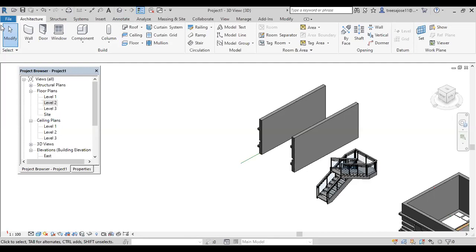Actually, with the help of roof by extrusion, you create the structure. Then after that, go to the void form. Then remove the internal structures. With the help of that roof by extrusion and the in-place mask, we can create the vault roof. After finishing this session on family creation also, I will show you. If I don't have the time, I will show you in the doubt section. But I will try to clarify this in this session itself.